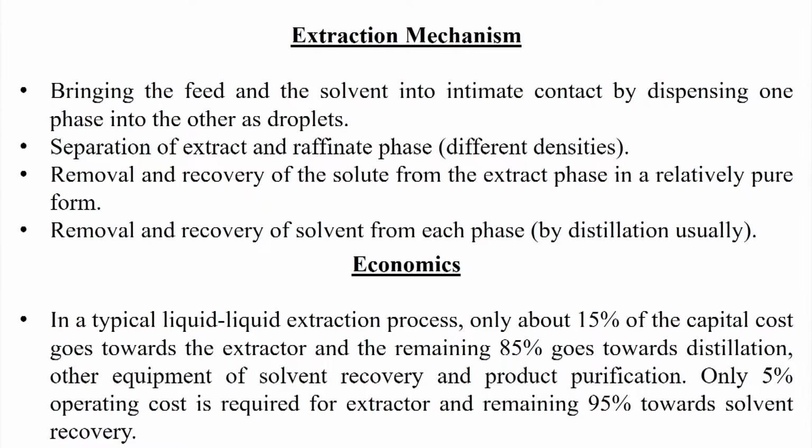Now, if we talk about the economics of the extraction process, it is very interesting. In a typical liquid extraction process, only about 15% of the capital cost goes towards the extractor, and the remaining 85% goes towards distillation or other equipment for solvent recovery and product purification.